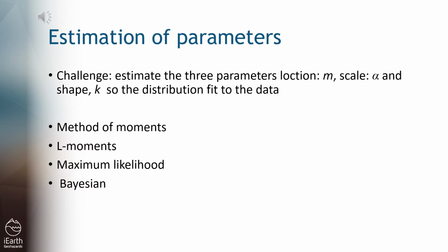The fourth approach is a Bayesian method. Then we use the likelihood as defined for the maximum likelihood method, but we might add some prior knowledge about floods. This is typically restrictions on the shape parameter. And a benefit of the Bayesian method is that we get uncertainty estimates for the design floods. The recommended methods are L-moment or Bayesian approach, since they are both more robust and not too sensitive to outliers in the data.